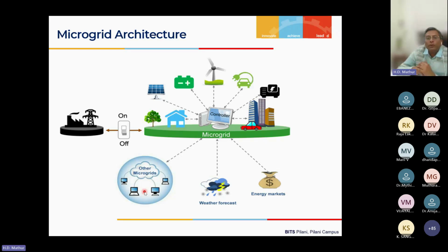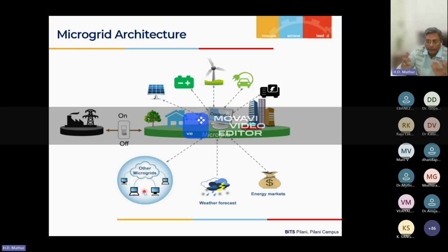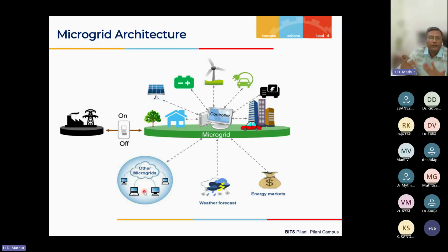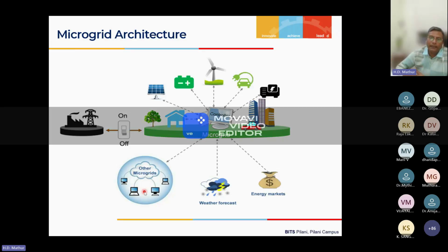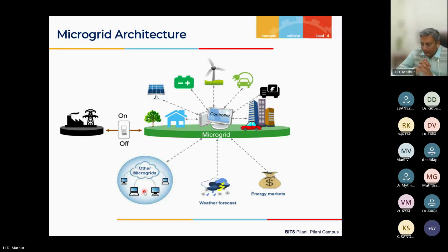So in order to make it more robust, on the basis of available data, we have to develop certain techniques which can forecast solar irradiance and wind speed throughout the day, at least a day before, right? That will help us in optimizing the scheduling of our hydro and thermal power. So therefore, this is needed in general when we talk about national level grids and other larger systems.